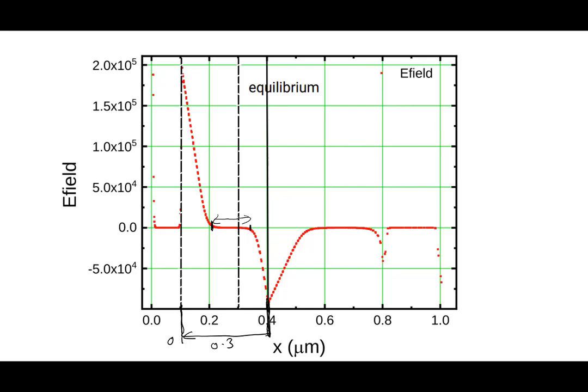Now as you forward bias the base junction, this point will move left because the depletion width will shrink. And as you apply reverse bias to the collector base junction, this will also move here. So when you take a bipolar transistor like this, consider the following situation: ground, ground, and ground. This is the situation that I'm showing you, and the device is obviously supposed to be off, correct? Equilibrium, no current is flowing, this is fine.